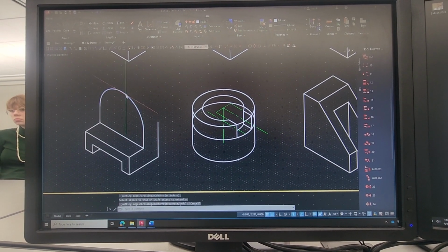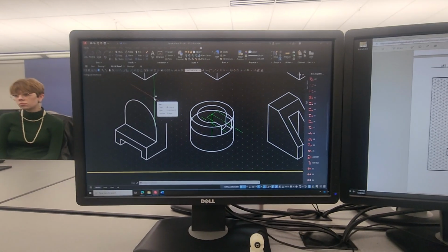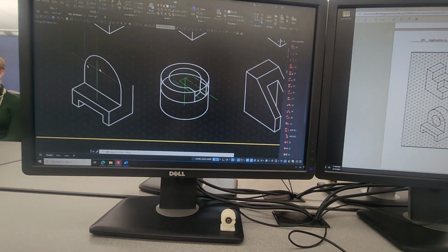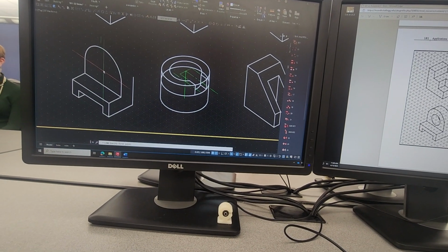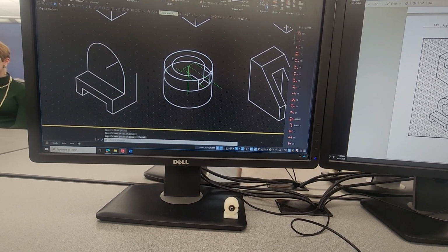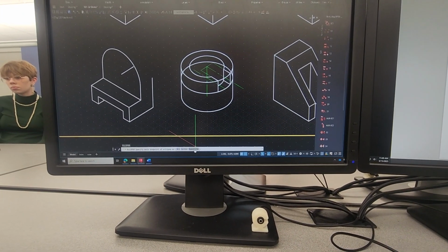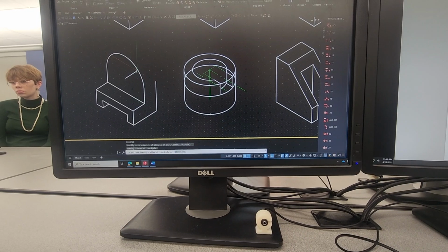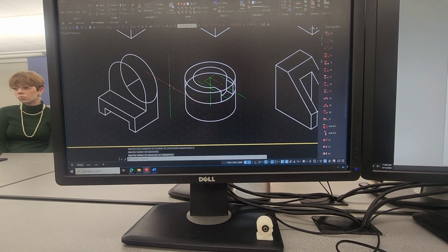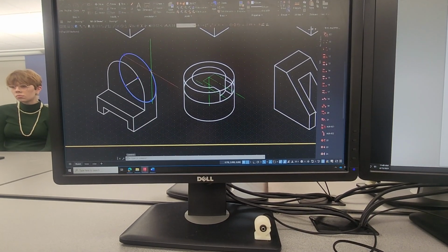Now, what I'm going to do now is this. I've got two different methods to get the same thing back here. What could those two methods be? Well, I could do the exact same thing again, just recognizing that I'm going from the center point here, where it was before, going back 2 units to a center point there, and I can create the next EL isocircle from that position, and it should give me that location right there. You see what I've done? That's one way to do it, or I could have simply done what? I could have copied the one I already had, right? Because they would be exactly the same.